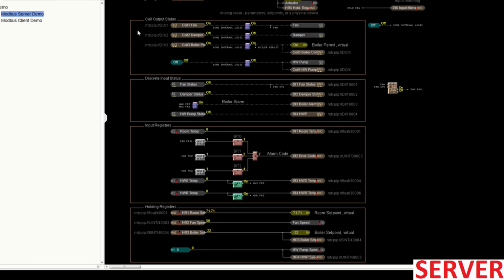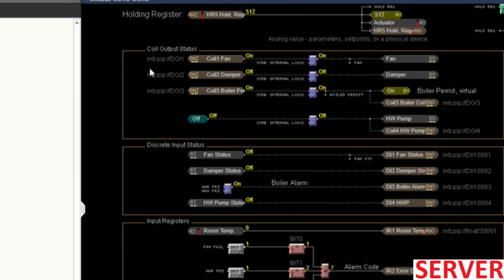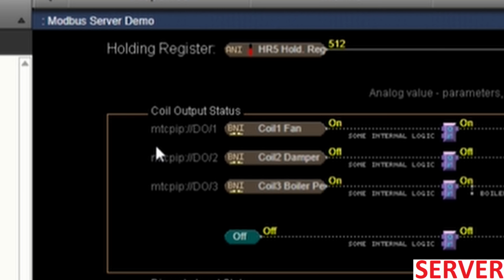Down below, I've again used these building blocks with dummy logic for a sample program, which directly represents the demonstration memory map and is symmetrical with the client program. I've again labeled each network point with the address on the server side, telling the controller where in memory to store each variable, which then will be the location that the client references.